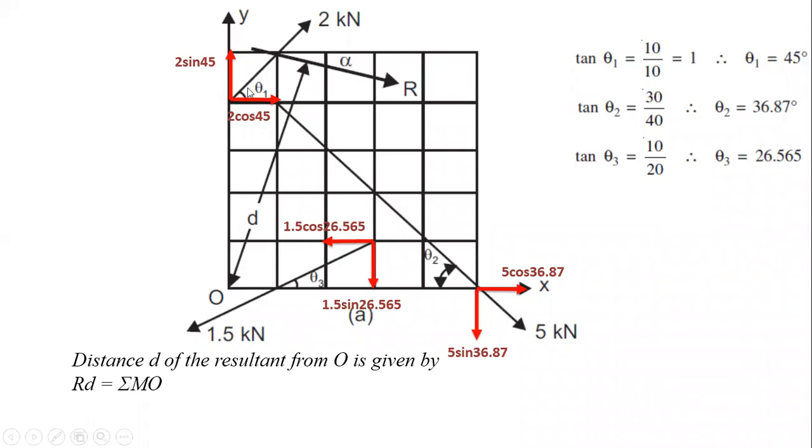If we are considering the moment of this force and this force about point O, it is producing the same moment which is caused due to the resultant R. Now let us check it out. Now this resolved force, which is passing through the point O, we are not considering this force, because the perpendicular distance for this force is 0. Okay, now the next one.